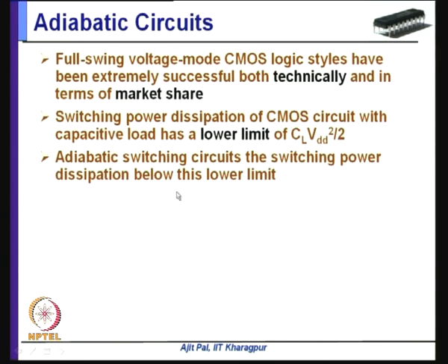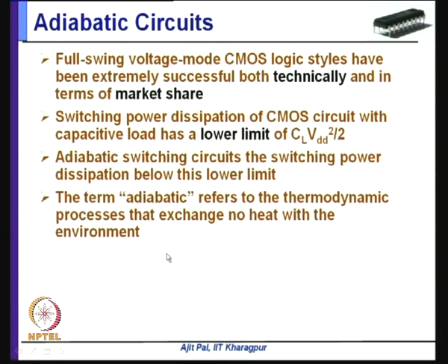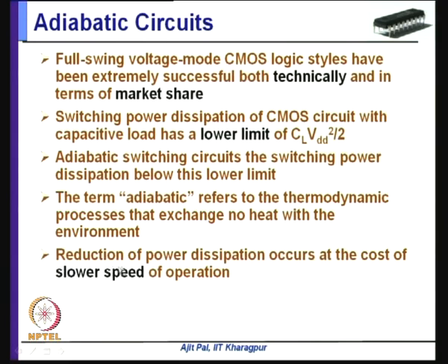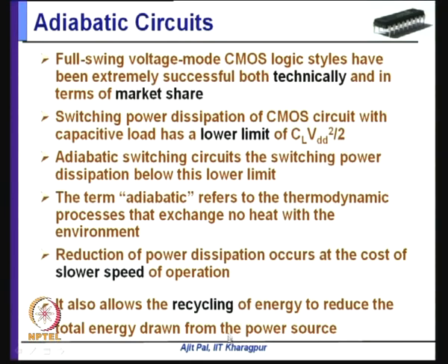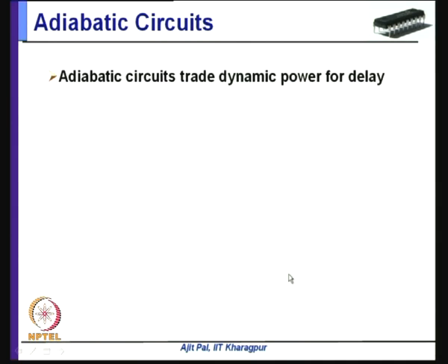The switching power dissipation achieved is below this limit. And actually the term adiabatic refers to thermodynamic processes that exchange no heat with the environment, and this reduction of power dissipation occurs at the cost of slower speed of operation. And also in adiabatic circuits, this recycling of energy can be achieved, which I have discussed in detail in this lecture series.